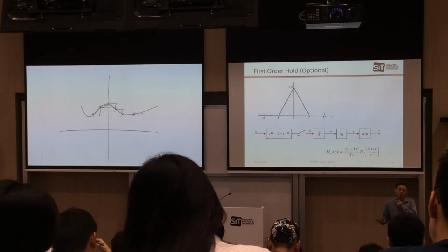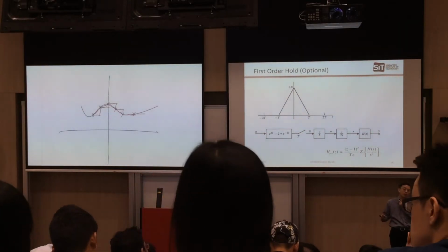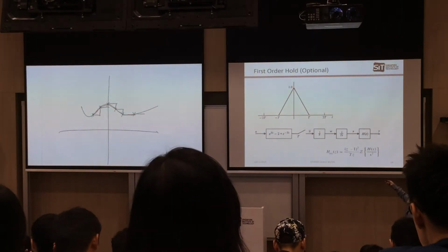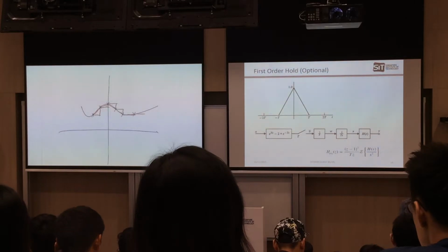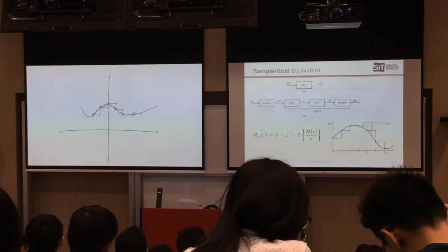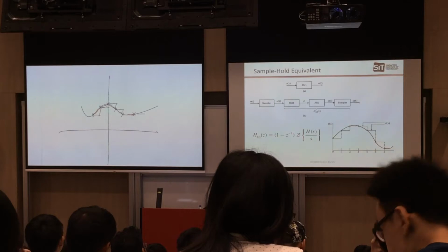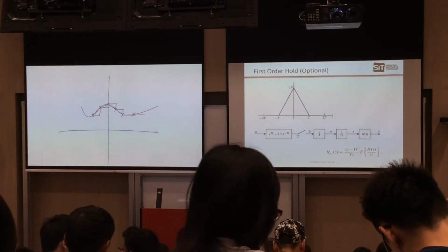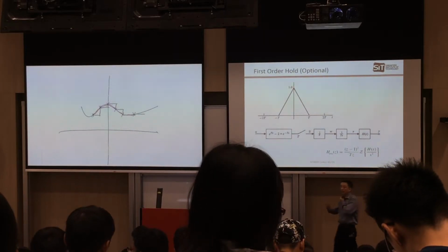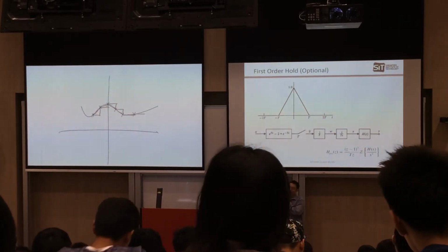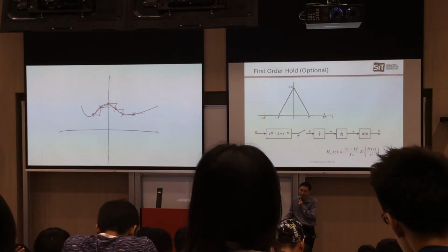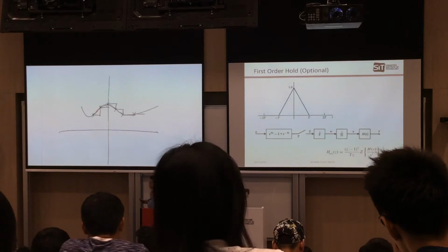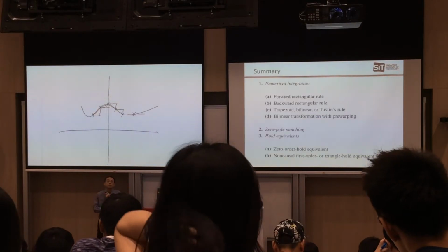Okay, similar to your zero order approach, but you use the H(s) function divided by s squared. And you multiply with (z minus 1) squared. So compared with your zero order hold, which only divides by s and only multiplies with one order, for your first order you have to do two. So you can predict for second order, most likely you have to divide by s again, right? Okay, for students with interest, you can refer to the textbook for more details.